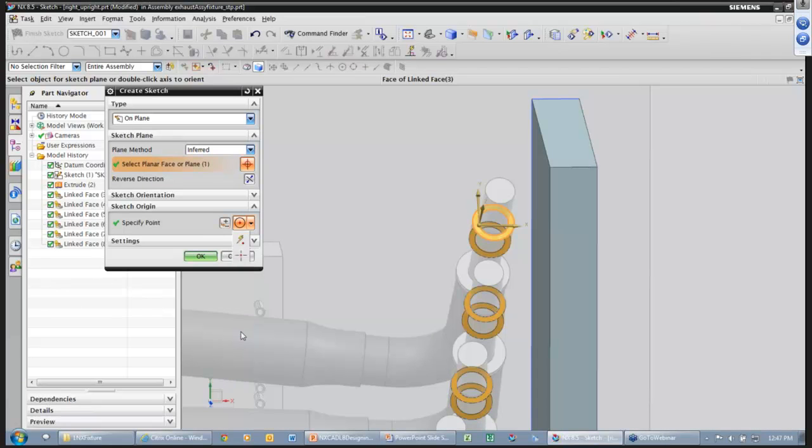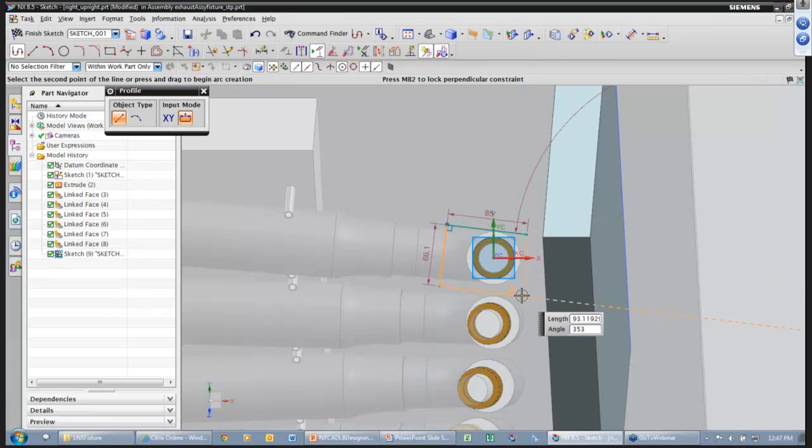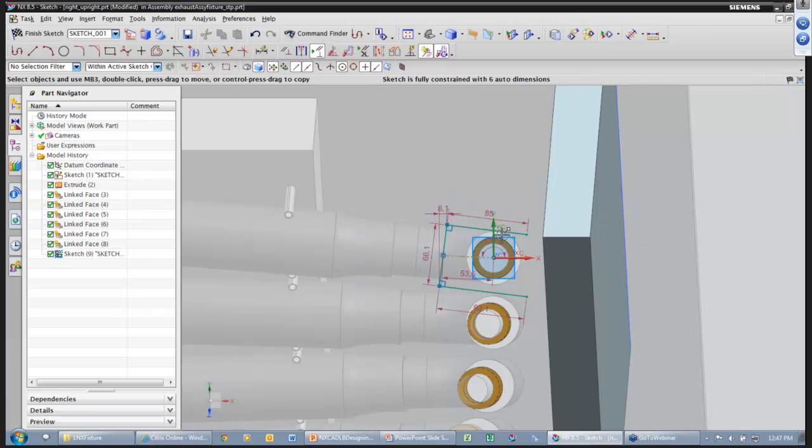I'm actually going to go ahead and move my sketch to the center. So I'm just in the sketch environment. I'm going to come off and pull some rough geometry off of there using profile. I'm going to come in here and build a little center line for construction. I'm going to toggle that guy to construction so that won't be picked up from the extrude command. Add some constraints there. I made a parallel constraint. How wide do I want this to be? I want that to be 50 millimeters from the left off center, so I have enough meat over there.